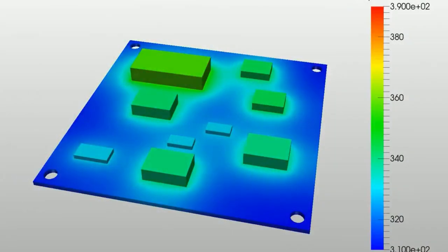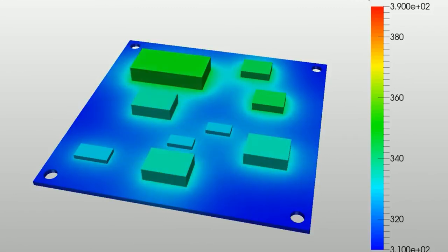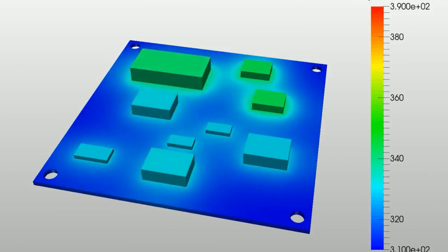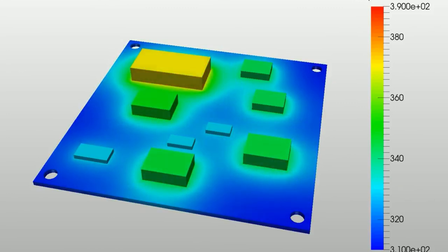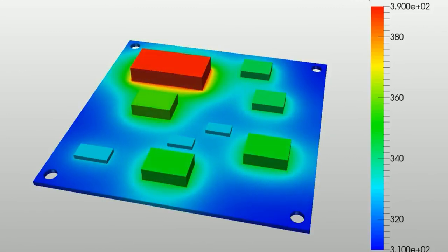The other tip I want to share is to figure out the trace width. When you have electricity coursing through all of your copper traces, it's going to produce some serious heat. And this is always a concern with electronics. Controlling the width of your traces is one of many ways to reduce how much heat builds up on your board. And the wider your traces, the less resistance that electricity will encounter when flowing through your circuit.